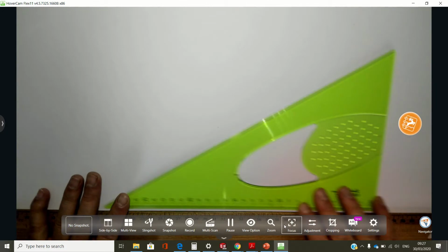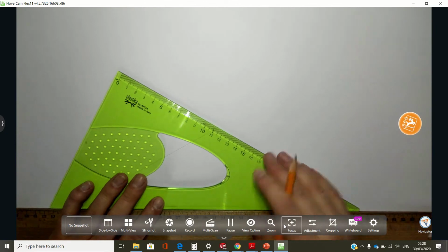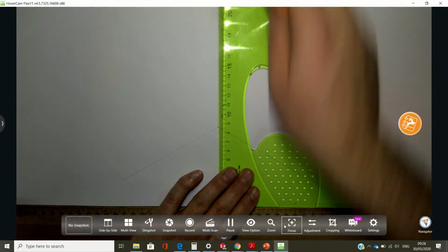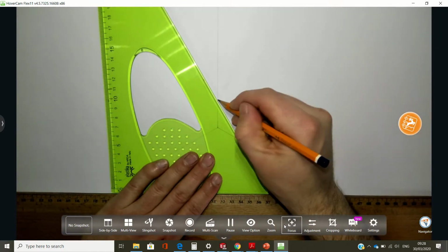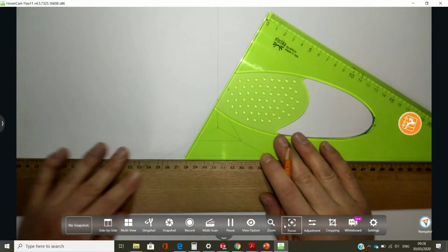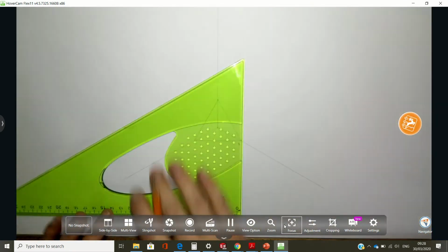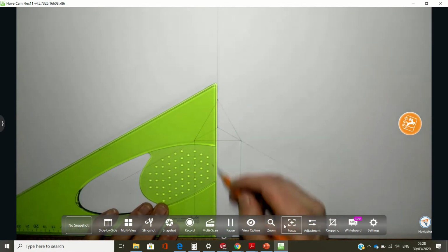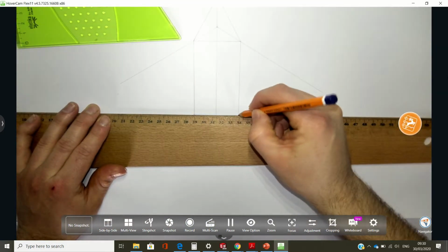So I'm going to start by drawing my axes. So both axes are at 30 degrees. Okay, and then to set up the views at the required angles, I'm going to use an equilateral triangle. Okay, so the size of the triangle is irrelevant. It just has to be equilateral. To drop the corners down here of the triangle, they can go to any depth you want. So I'll go down 80 just for suggestion of size.